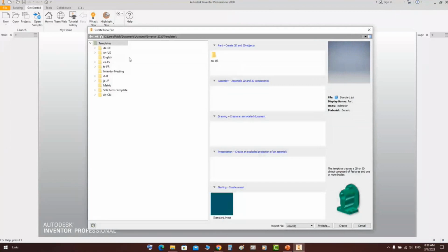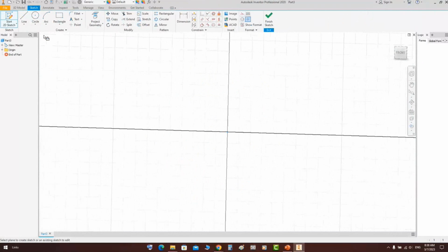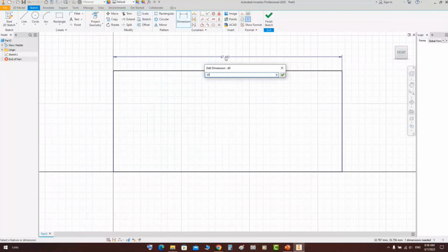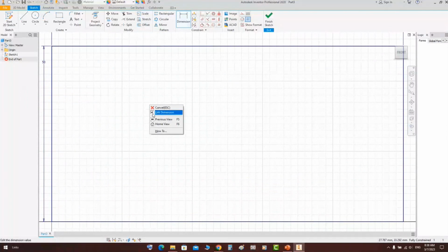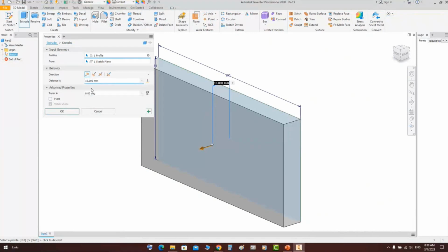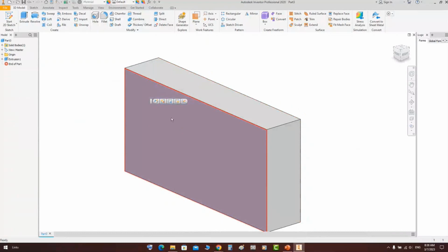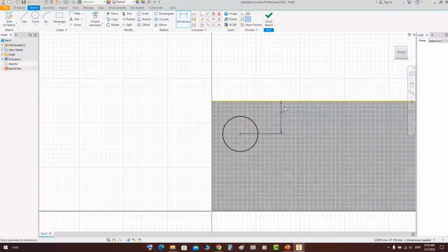Now let's create a new part. Select this plane, for example, and from here let's create that one. Millimeters, and make extrude. If you select extrude from here, give a value of 20 millimeters. Select this surface. Now you have a plane here. You will select it and create a new sketch. Then let's draw a circle. So define the location of this one, like that.